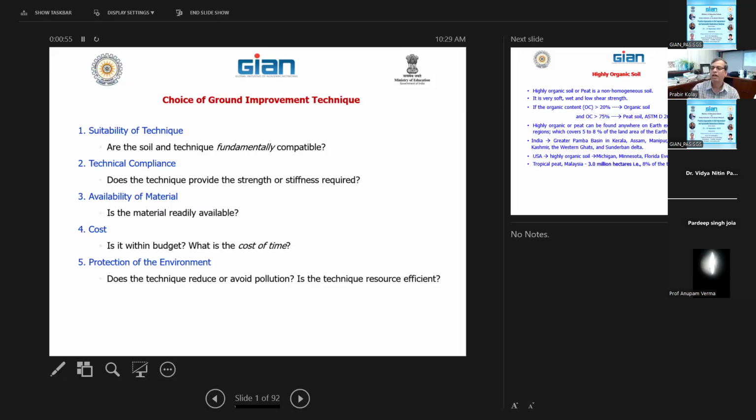Yesterday we talked about sand drains. We talked about prefabricated sand drains, and then PVD drains. And then the chemical modification. And yesterday we talked about the different chemical admixtures you need to use. The conventional admixtures, cement and lime, and industrial waste, fly ash, GGBS, and others. And then we talked about non-conventional ones, you can use polymer, different geopolymers we mentioned, and then the durability of that. And then the last part is inclusion, something you include into the soil.